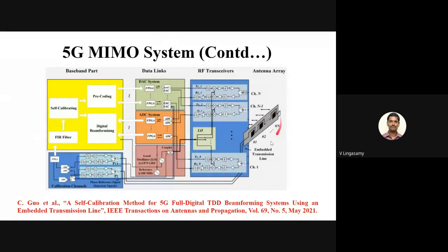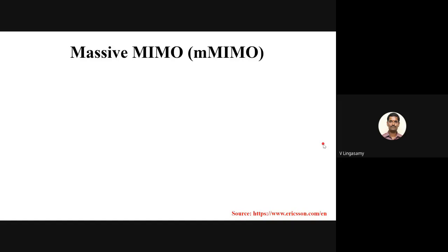So I have to align my power accordingly so that I can reach that user with at least minus 65 or minus 70, like that. So accordingly I have to calculate what should be the output power of my radio, so that it compensates for the path loss and then reaches the user. Okay. Next, we will talk a bit about massive MIMO.